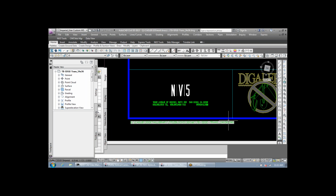File etiquette. I know we talk about it a lot because it's very important to me personally, and I think it's important to everyone here. When you open a file, you want to be sure that all the settings are set correctly so that you can actually start working. The last thing you ever want to do is open a file, start XREFing a file in and going, oh, why isn't my XREF appearing? Oh, it's because the last person in the file set the UCS to view or UCS to object or something like that. So 2 simple things can really help with that. Just make sure that you treat your files correctly.